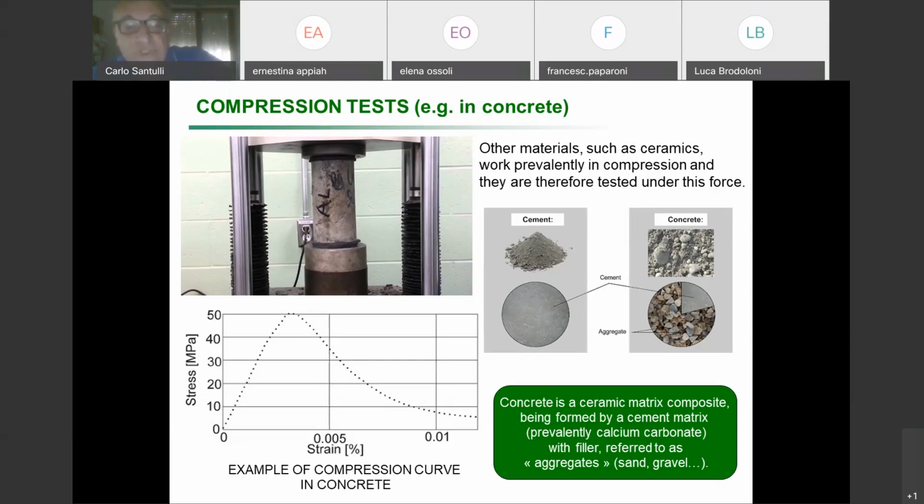Then you would have some... you don't have a real necking, because what happens is that the effect of shear becomes evident, and it's a different kind of necking. You wouldn't have necking on the middle side, but you would have some breakage on the extreme parts of the cylinder by shear, some part detaching and so on. Okay,